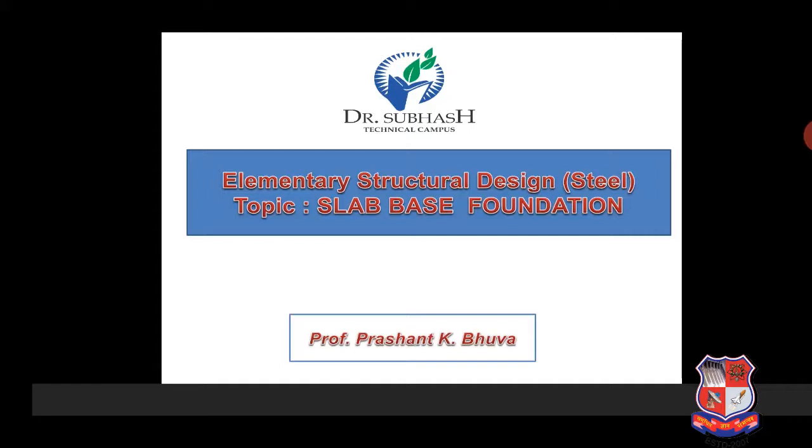Initially the column load is distributed over the base plate and the supporting concrete, and finally to the soil below, such that the bearing capacity of soil is not exceeded. So mainly 3 stages: the column transfers the load to the base plate, the base plate transfers the load to the concrete block, and the concrete block finally transfers it to the soil, or you can say our foundation. There are 3 main types of column base used. First one is slab base, second is gusset base, and third is pocket base. But in general we can use slab base foundation.